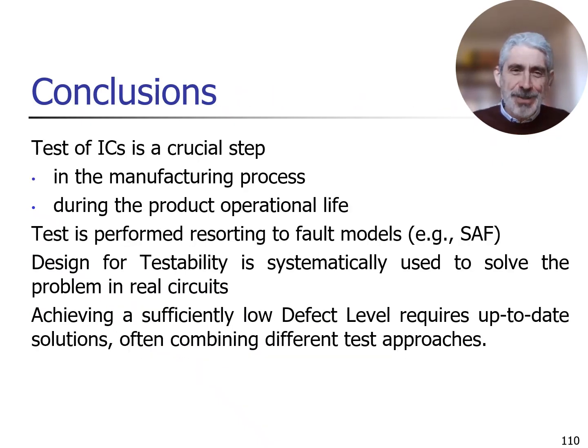Conclusions for my talk. Well, I hope I convinced you that test of an integrated circuit is a crucial step, both at the end of the manufacturing process and during the product operational life. For implementing test, we resort to fault models, and we use the stuck-at fault model as an example. I introduced to you the key idea of design for testability, which is systematically used to allow the test of real circuits.